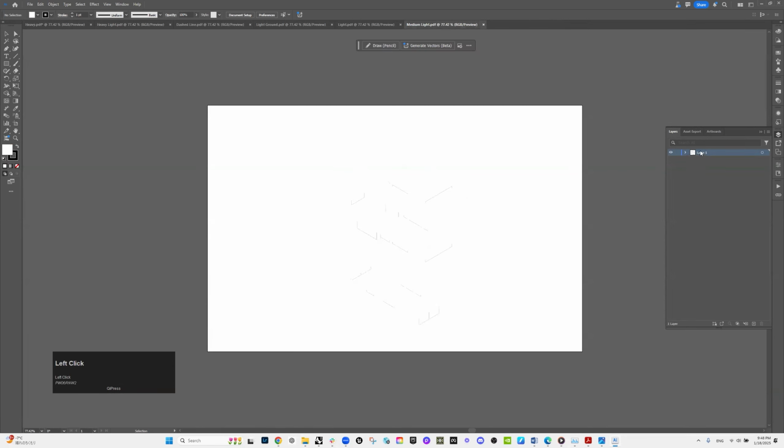And I'm gonna repeat the same process, medium right. So first change the name of the layer and select everything, Control C to copy, go to the heavy line weight file and type Control F to paste the lines in the same locations. And I'm gonna do that for all the other files.